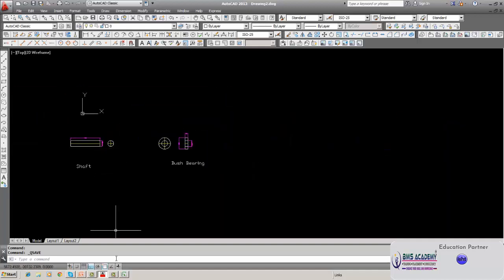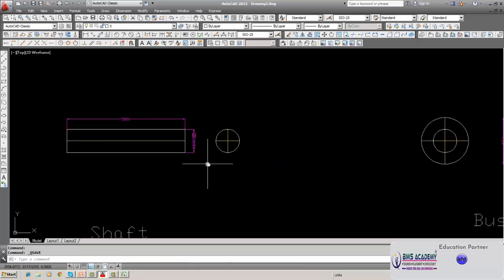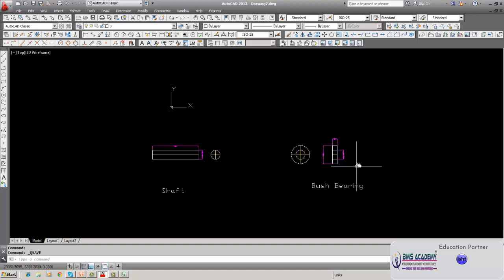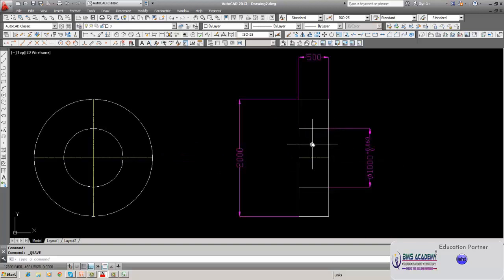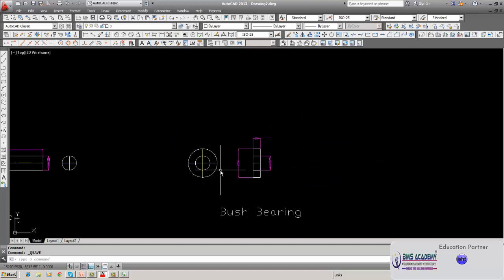So the shaft always has a clearance so that it can run. But it is a rough running. So if you want very slow speed, it can run. If you want high speed, the clearance should be made very small. It can be made as small as zero point zero two, 20 microns, 0.02 can be made. Then the process you have to adapt to different machining processes, grinding or machining or super finishing, some such mechanical processes. Same way the bore also we have to adapt. Okay, this is how we can do tolerance.